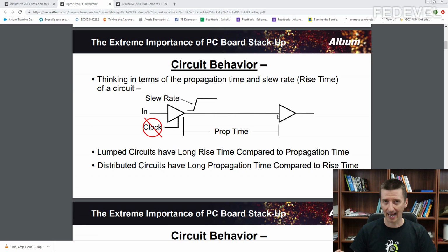Okay, so in reality, when this change travels through this line which is here, then for example, when this change is somewhere in the middle of this line, then on one side of this line you can have, very simply to say, for example, logic level high, and on the other half of the line you can have, for example, logic level low.